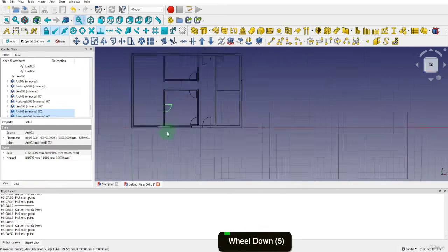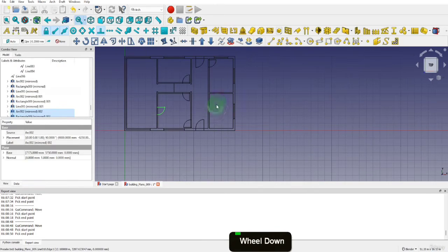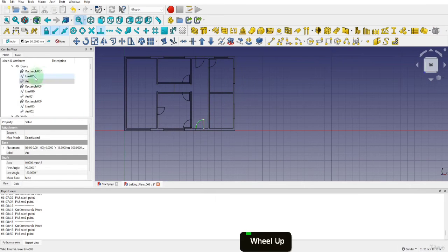Now there are two things left to complete. The first is one final door on this wall here. This is an external door from the garage. It's the same size as the external doors, except the rectangle needs to be 150 to match the width of the wall. It's also 650 from this wall here. Your challenge is to make a duplicate of the external door, modify and fit this into the wall.